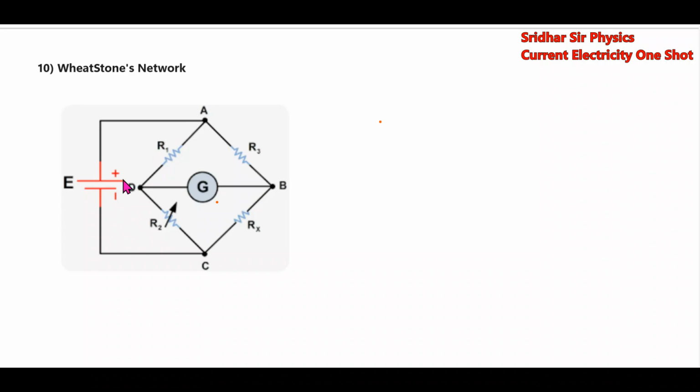Next we have the Wheatstone network. The potential when the current through the galvanometer will be 0. So in fact here current will flow like this. I, this will be IA, IB. The current here, it will not branch, it will remain same. So this will become IA. Here also the current will not branch. So the same current will flow, and this is the I.